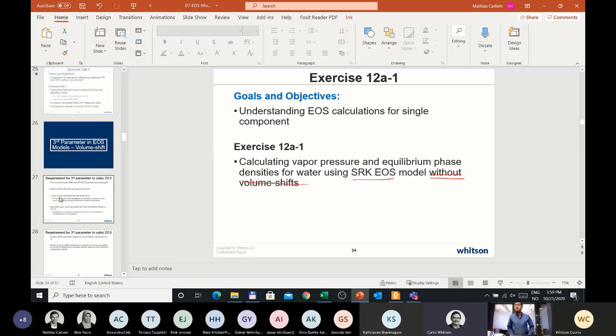Yeah, so the equation of state will never get the compressibility of the high pressure gas or oil right. That means that your recoveries are going to be wrong. The material balance it calculates in your simulator, every grid cell, will be wrong, okay? And maybe significantly wrong. You could try to use a black oil model, but the problem with that is it's generated from the equation of state now. So the black oil tables would have the same poor compressibilities at high pressures because they're generated from the equation of state. So you have a problem with high pressure gas and oil reservoirs in reservoir simulation.